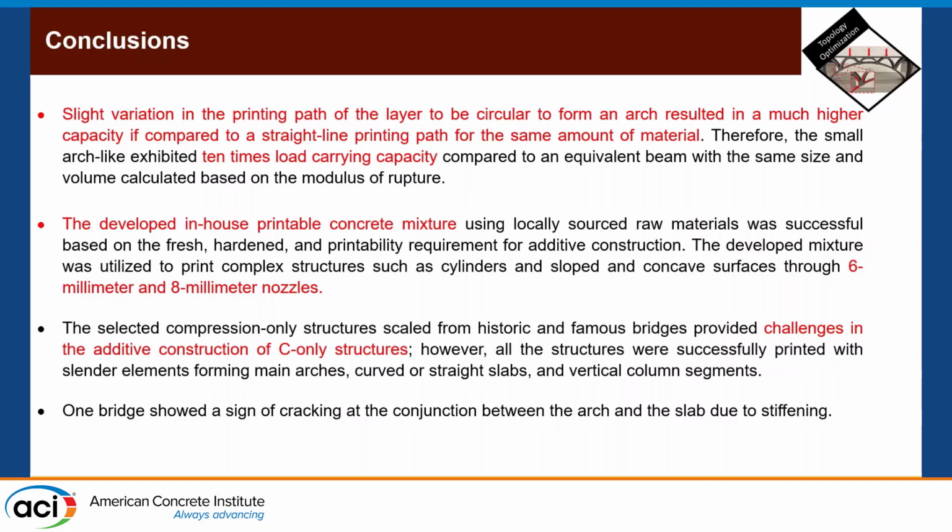We have more than 300 printing hours since last year. We were able to print out of a 6mm nozzle and an 8mm nozzle. We were also able to print a 1 foot structure last week. We have challenges on that, and we will start testing those structures that we just printed really soon. The stiffening at the joint created cracks, which I believe was because of the restraint at the joint, not allowing the entire structure to shrink as one unit.